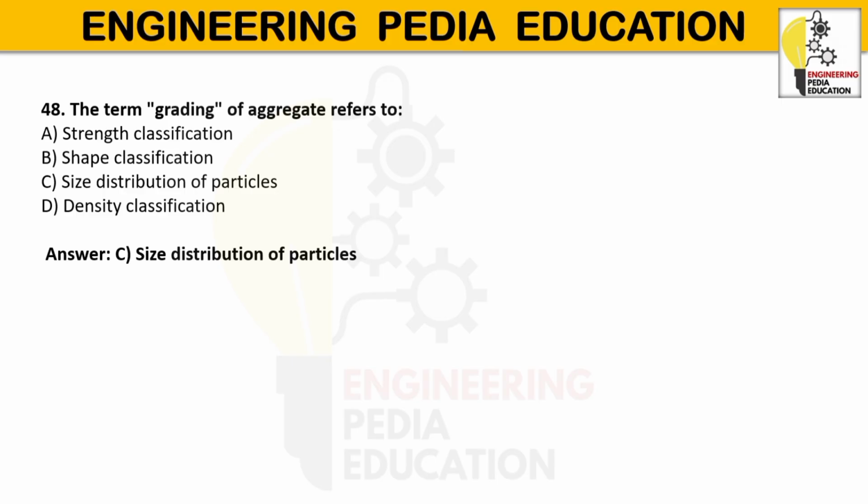Grading of aggregate refers to the distribution of particle size within a sample of aggregate to ensure proper workability, achieve maximum density and minimum voids, improve strength and durability, and reduce cement requirement. Types of grading are well graded aggregate, poorly graded aggregate, uniformly graded aggregate, or gap graded aggregate. Determination of this is done with the help of sieve analysis test.